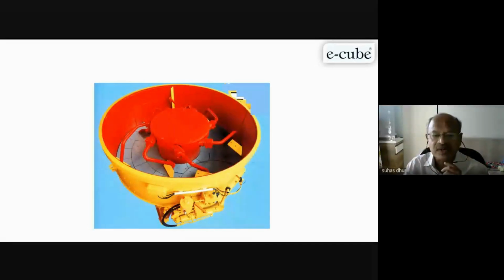And this is a hydraulic door, which you can see here, and it opens and discharges the concrete. Now water is also not put in directly by a hose. There are a lot of spray nozzles which spray the water during mixing and evenly mix the concrete very properly.